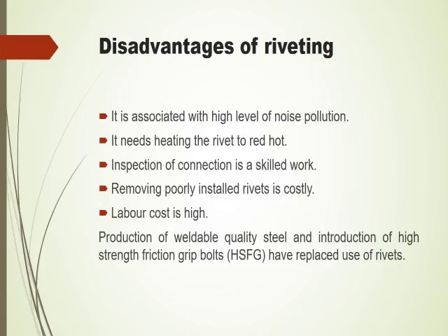and inspection of connections is skilled work. And removing fully installed rivets is costly, because we insert the rivet and make a head on the other side, so to remove that rivet we have to remove one head. So it is costly, and labor cost is high.